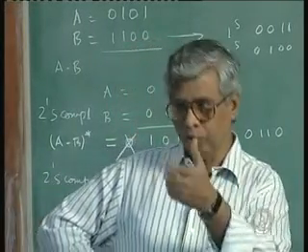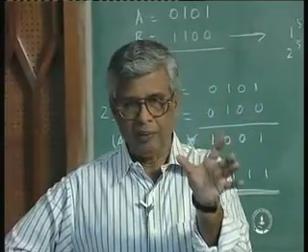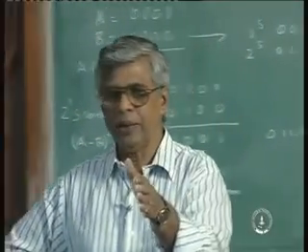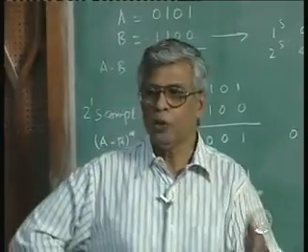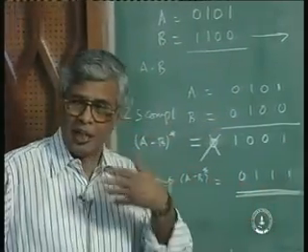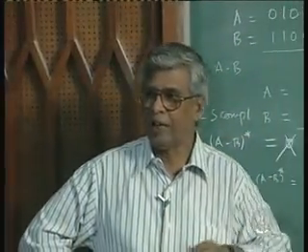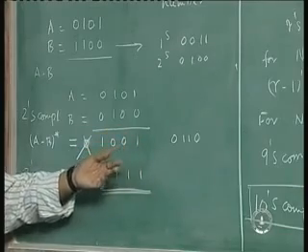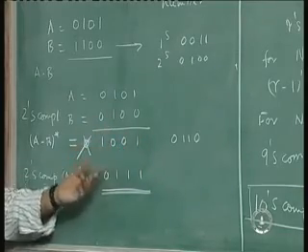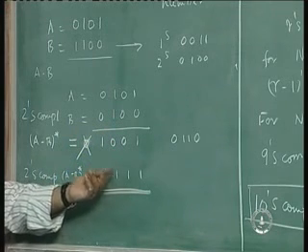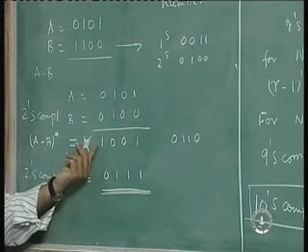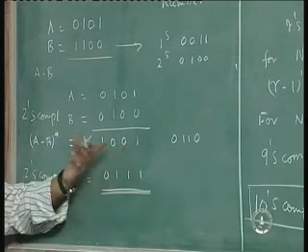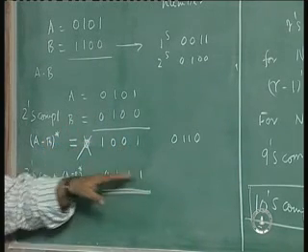So in any number of bits, you define the number of bits in a number. The most significant bit, if it is 1, it is a negative number. If the most significant bit is a 0, it is a positive number. So even though it's for our understanding, to make sure that my arithmetic is right, I want to do this 2's complement and check whether it's really 7. I knew it is 7, I knew it is negative, but I am not sure it is 7. How do I check it is 7? By taking the 2's complement and finding out it is indeed 7.